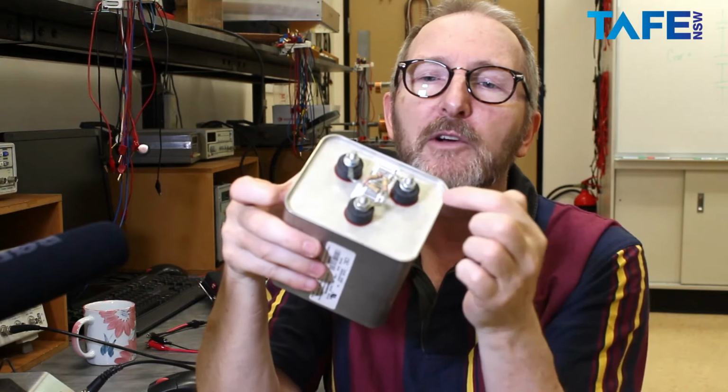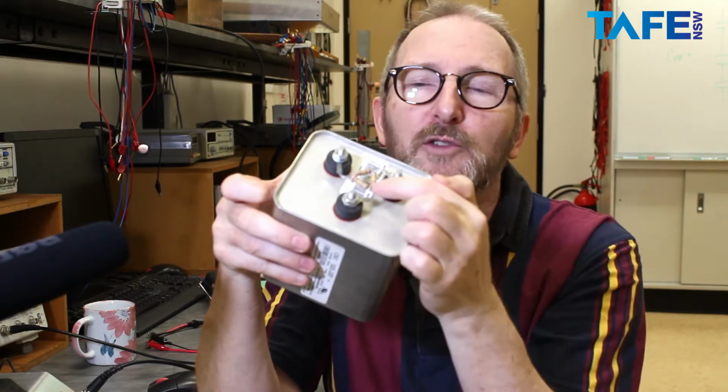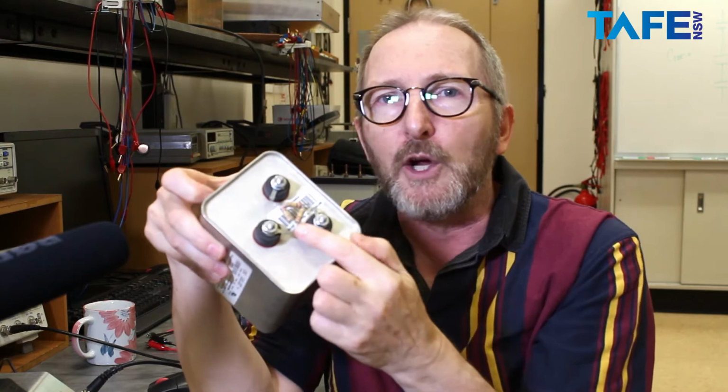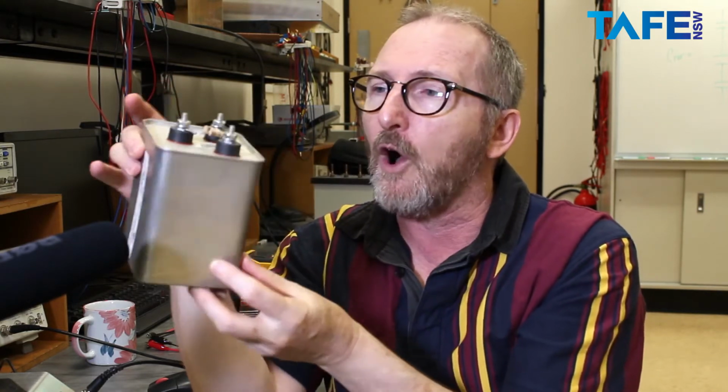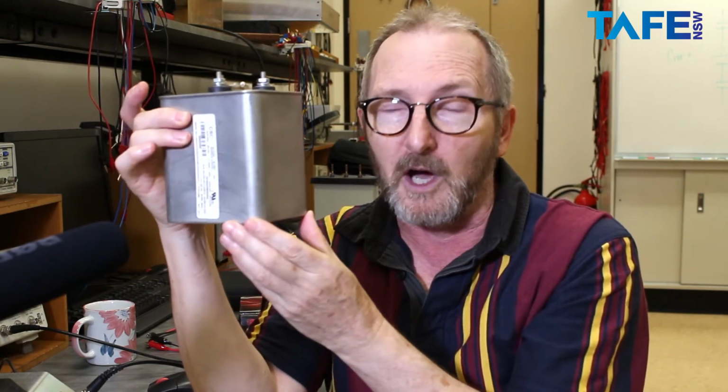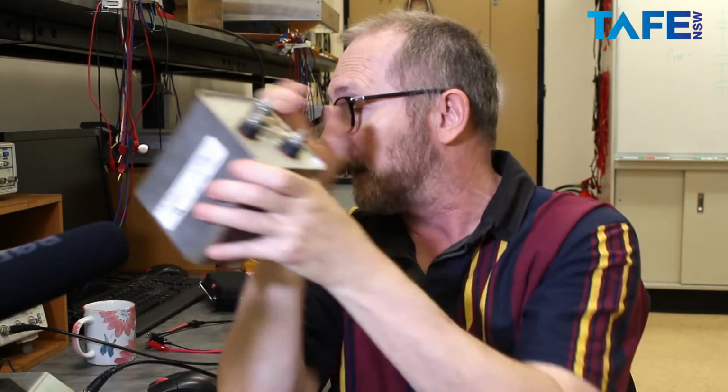This capacitor is very interesting. I wouldn't be putting my fingers across the top if it did not have these bleed resistors. It has some 120k resistors across each terminal on the capacitor. That is because if we leave this capacitor in a charged state with several joules of energy stored in it, and somebody was to put their hand across that, they could get quite a fatal electric shock, purely because of the high voltage characteristics and high capacitance value of this particular type of capacitor. So you should always have bleed resistors across big capacitors.